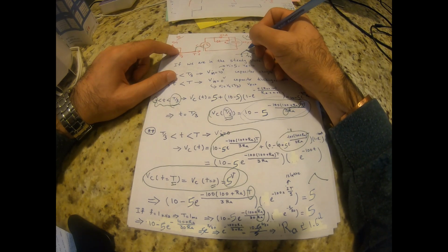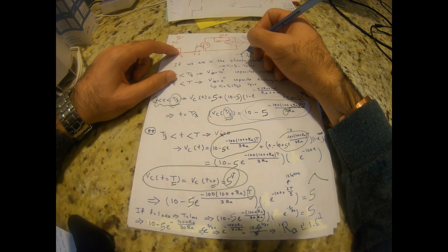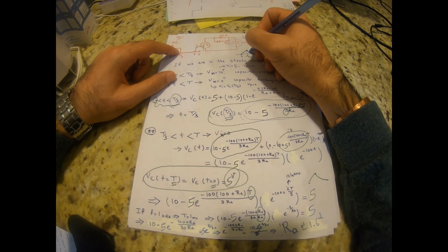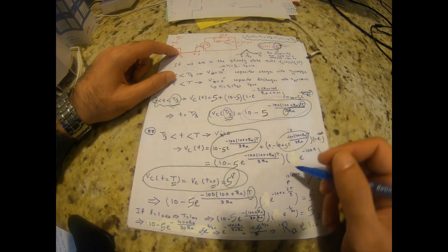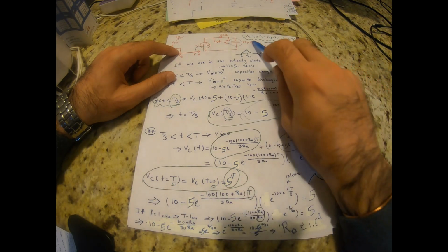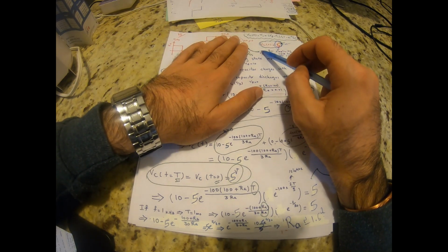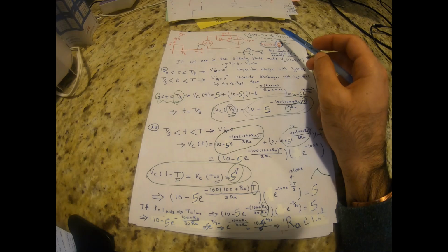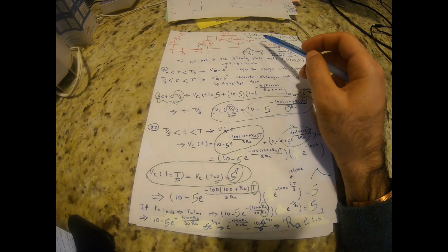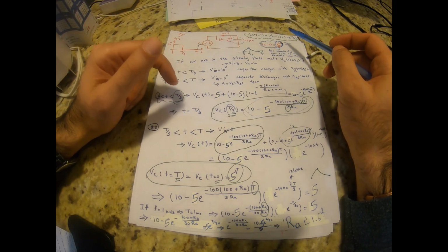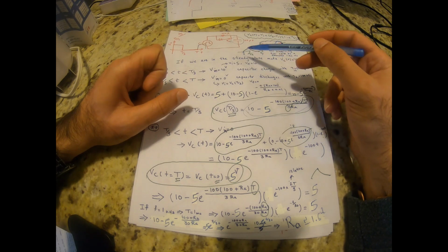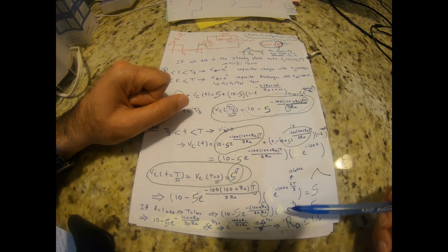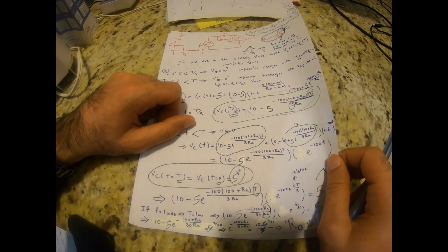Now, the amp-second balance tells us that if we want to end up in the steady state, the capacitor has to discharge exactly to the voltage that we started from, right? So I again wrote the same thing, but this time for the discharging period. I knew what my initial voltage is, I knew how long I have to wait, and I knew what voltage I have to end up at. So I did all these calculations and I find the value of RA.